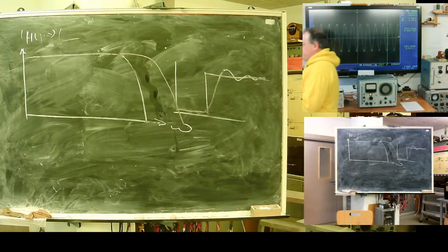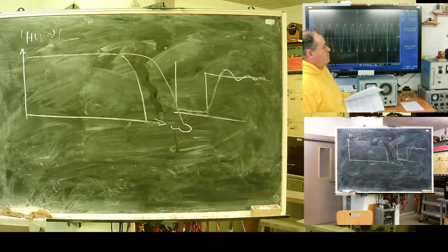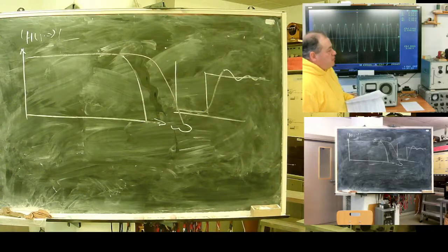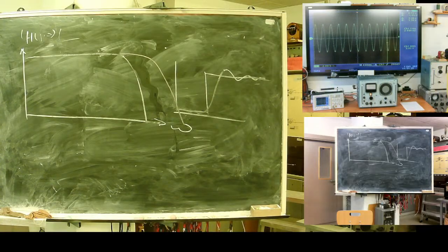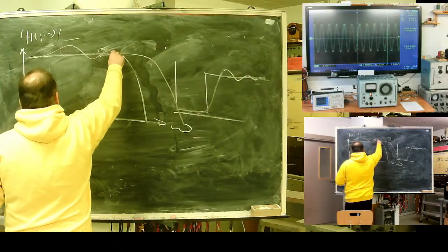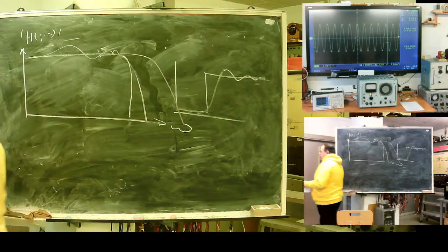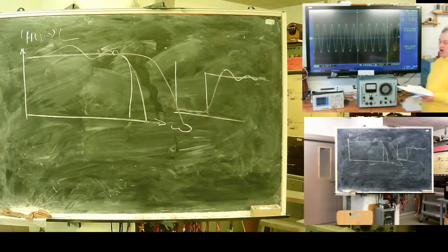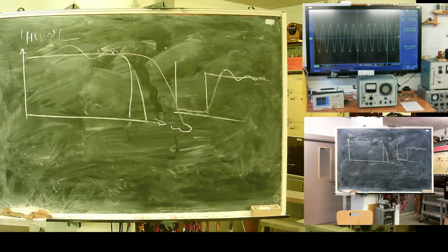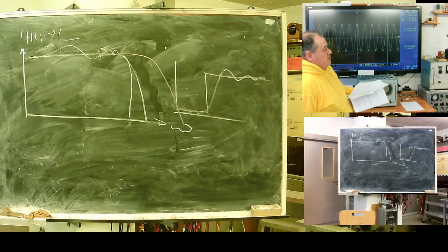Another one is a Chebyshev filter. Chebyshev's polynomials are polynomials with minimal distance from 1. Chebyshev's filter is kind of wavy and then very fast. Chebyshev filter gives a very sharp cutoff, but a filter based on Chebyshev polynomials has oscillations, kind of waves, in its passband.